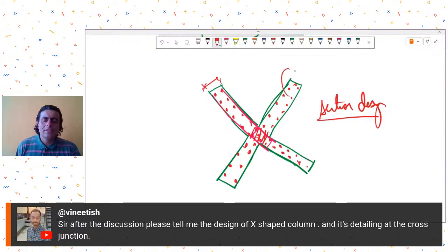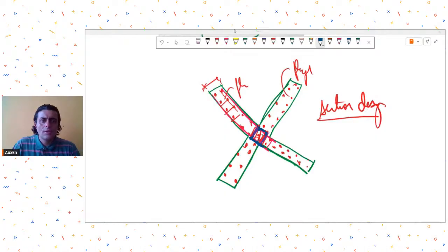Treat them as multiple flanges of your wall. As you would provide your reinforcement in a wall, provide similar reinforcement in the junction. Just ensure that you are able to provide lateral ties in two principal directions like this. Otherwise, there is not much need to provide a lot of longitudinal reinforcement in this junction. Just 4 bars at 4 corners of this junction are enough, and the rest continue as the common reinforcement arrangement that you give. If you have any specific question related to this, please share some sketches or any diagrams if you have.